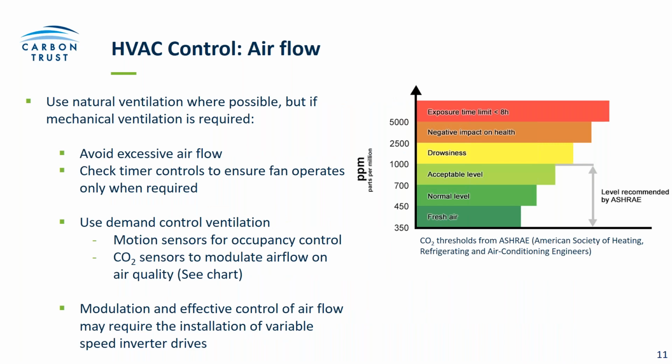The more CO2, the more people, and the more risk there is to poor air quality. But at the same time, when a space is lightly occupied, there won't be those same air quality issues, and the ventilation use can be reduced, thereby reducing the heating and the cooling needs. So essentially, that is an effective way of providing the ventilation of the space.